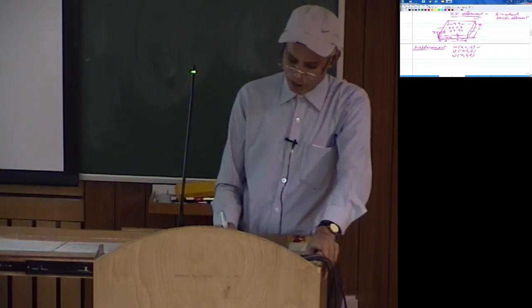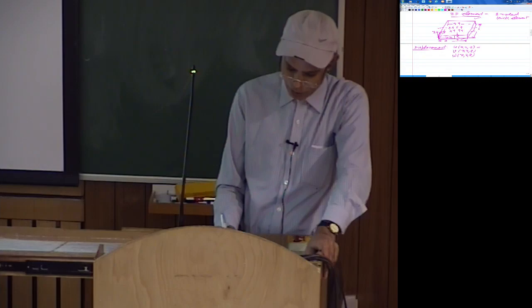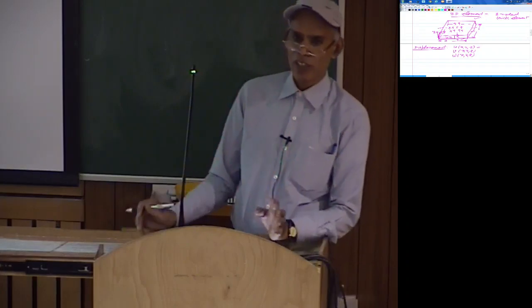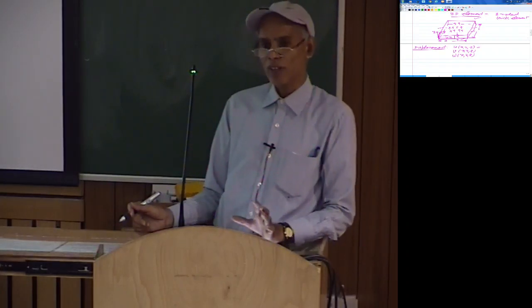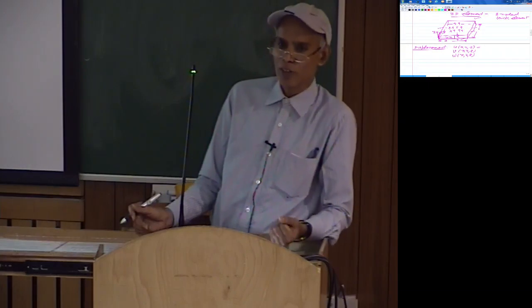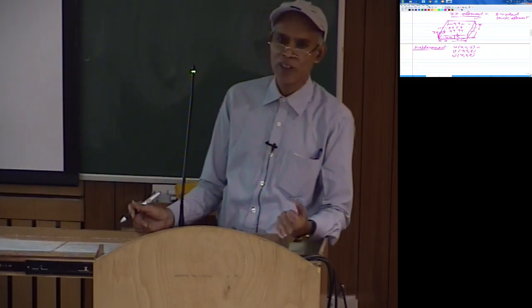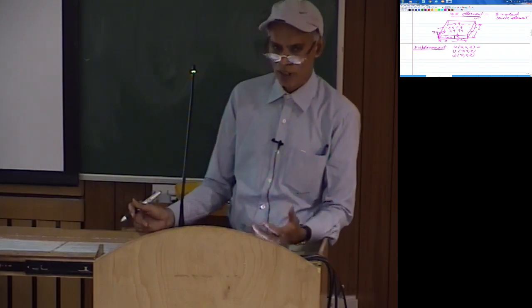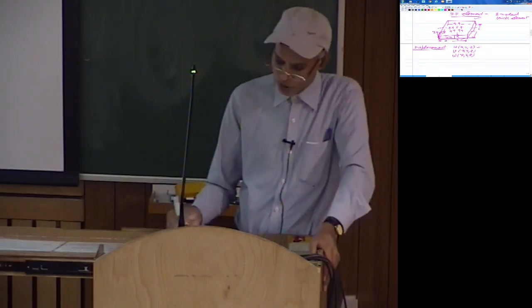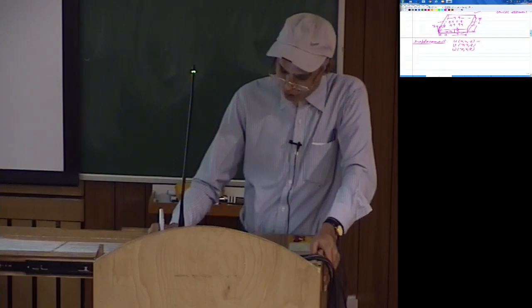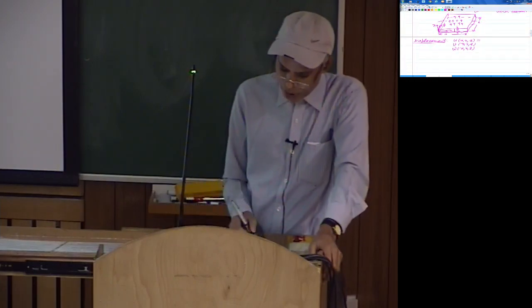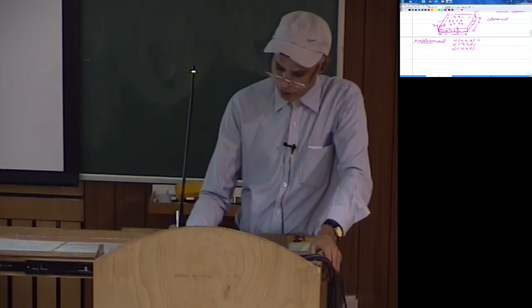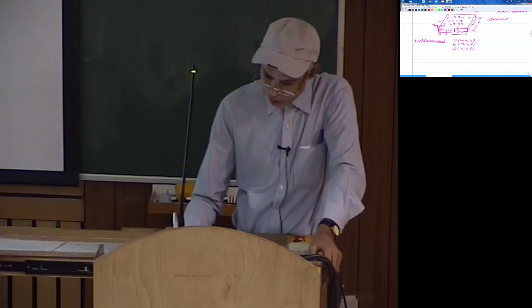That approximation is along the smaller dimension, which is this dimension. So rather than taking u, v, w unknown in z also, we take some known function in the z direction. Depending on what kind of function we choose, you have what is known as classical plate theory, Mindlin plate theory, or first order shear deformation plate theory, and higher order plate theories. So there are different theories. What I am going to discuss, of course only one of them, is the classical plate theory, sometimes referred to as classical Kirchhoff plate theory.